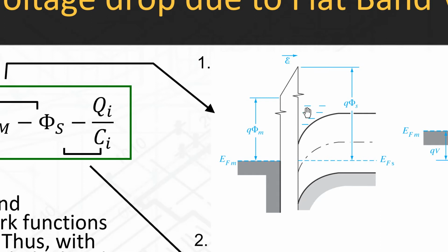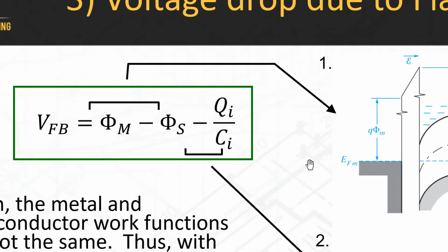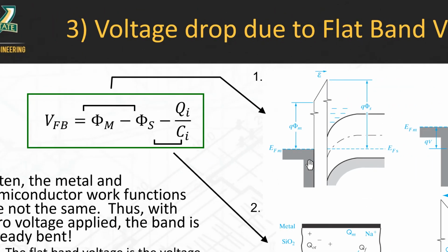And this diagram also shows that you have a buildup of electrons there. All right. So this diagram is showing you that if the semiconductor work function is significantly larger than the metal work function, you could get an inversion channel without applying a gate voltage to the material. That means the device is on all the time. Does anyone know what kind of device that is? Yes, it's the depletion mode device. A depletion mode device is the device that's on even when no gate voltage is applied. Right, so this is why you have to choose your metal and semiconductor work functions pretty carefully.